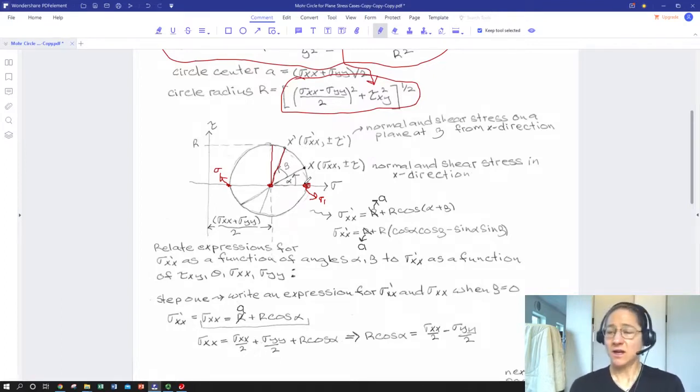Well, let's just take a couple of angles, and then let's think about how they would relate to the directions of zero shear and our directions of loading. So we're going to define 2 points on our Mohr circle, and those represent valid combinations of shear and normal stress that you're going to see somewhere in that body. If it's not on the Mohr circle, it's not a shear normal combo that body experiences at any angle. So these are like all the possible combos of all the possible planes at every orientation in the body, at least in the xy plane.